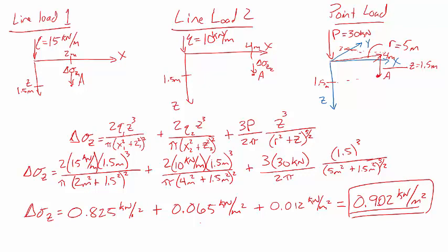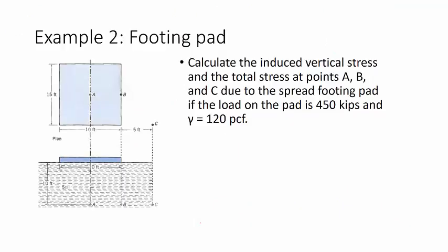Now let's go ahead and look at a little bit more complex of a problem. And as we can see here, we have a footing pad that is 10 feet by 15 feet, and we are asked to calculate the induced stresses and the total stresses at 3 locations due to this new spread footing that is to be constructed on this site.